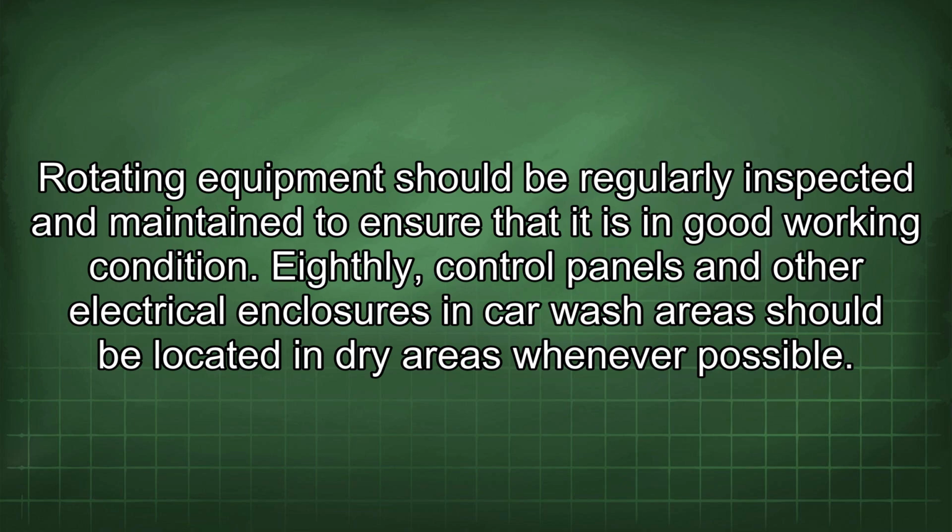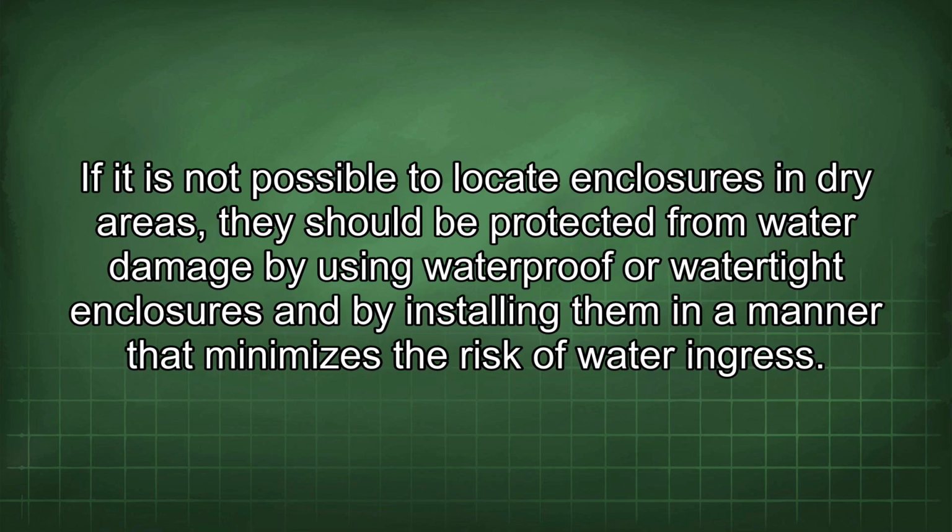Eighthly, control panels and other electrical enclosures in car wash areas should be located in dry areas whenever possible. If it is not possible to locate enclosures in dry areas, they should be protected from water damage by using waterproof or watertight enclosures and by installing them in a manner that minimizes the risk of water ingress.